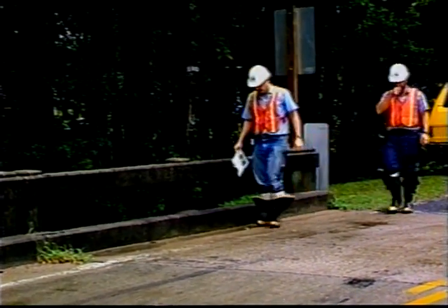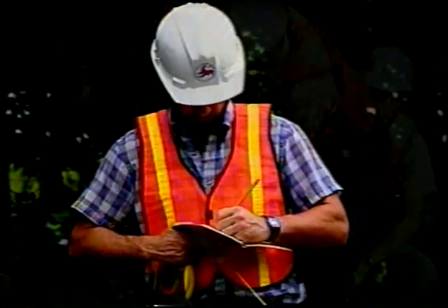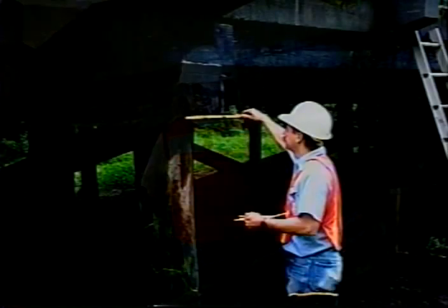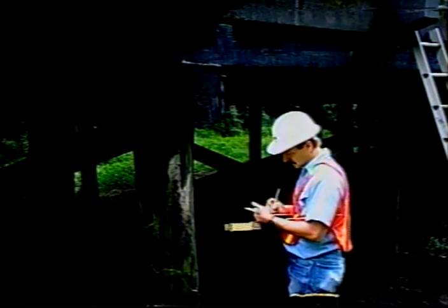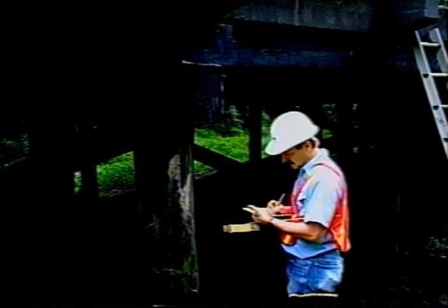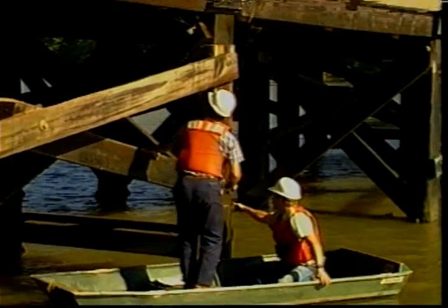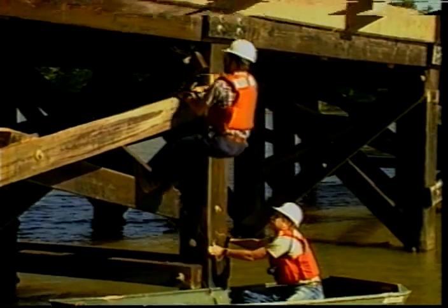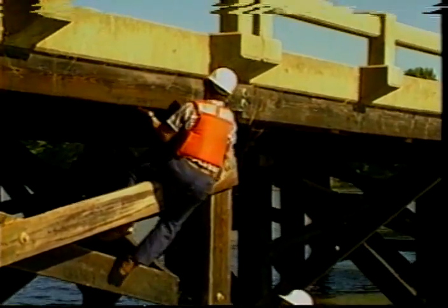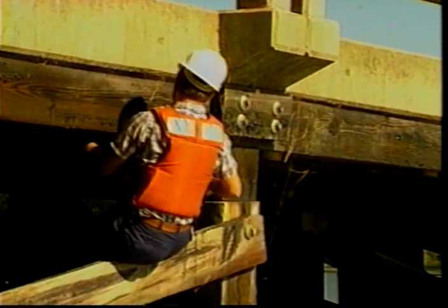The inspector's duties include planning and preparing for bridge inspections, inspecting bridge components for deterioration, sketching bridge components, photographing specific bridge problems, taking technical measurements, making basic computations, and maintaining inspection records. Bridge inspectors currently use many inspection techniques. Close-up visual inspection is the first procedure used by inspectors. Within arm's reach, the trained eye is the most valuable inspection tool. Several physical techniques are also used.